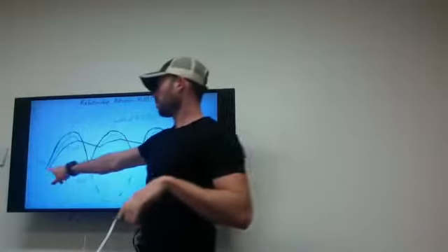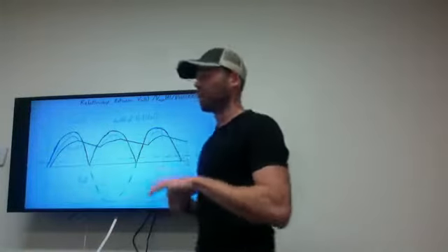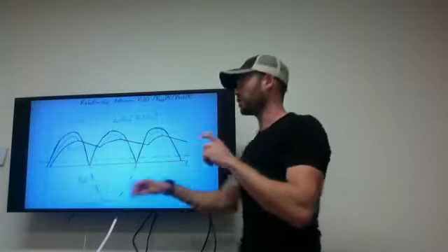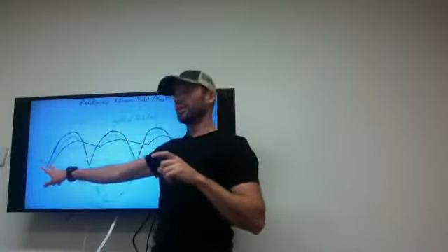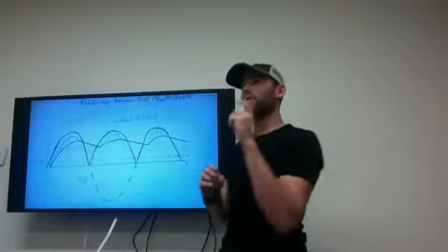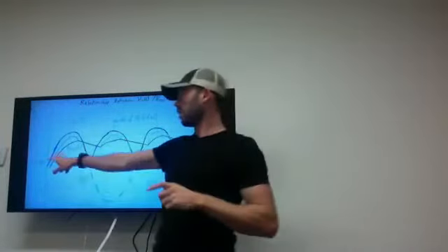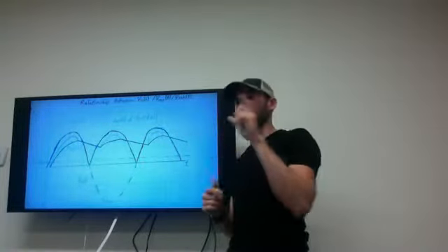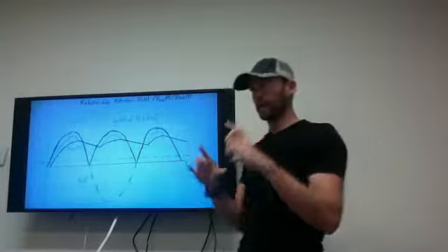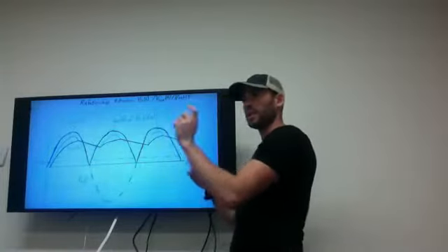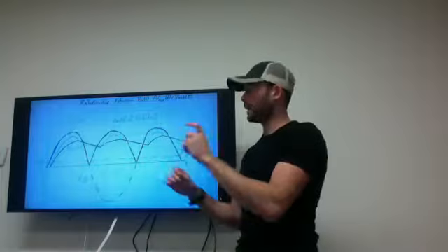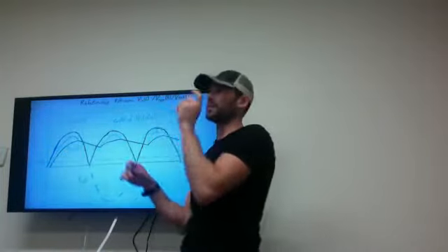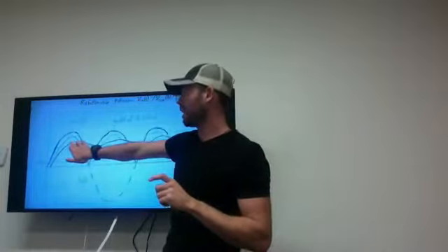This part right here is V rectifier. That is the voltage directly after the diode bridge, and it is the voltage that is going to be charging up the capacitor that will be used to smooth out the signal. If we look back at our circuit diagram, the resistor R1 before we get to the capacitor has a voltage drop across it, which is the current times that resistor. So that's the difference between here and there.